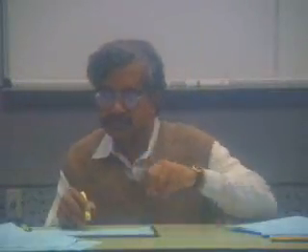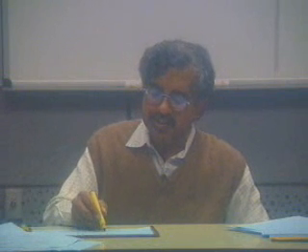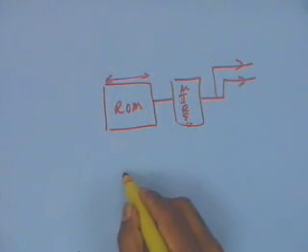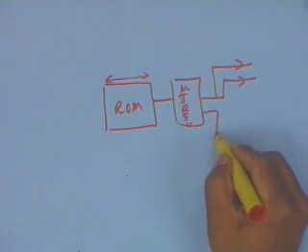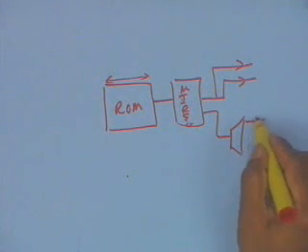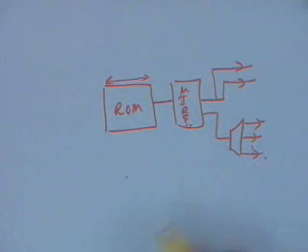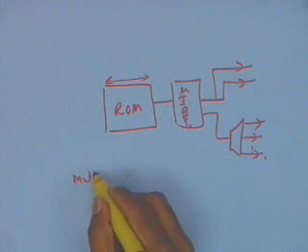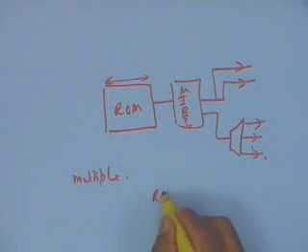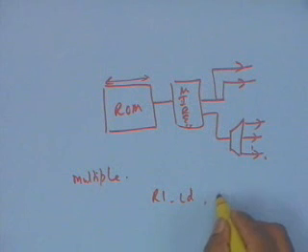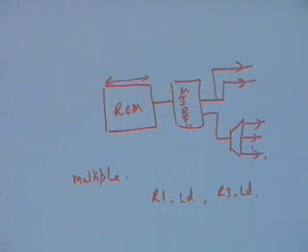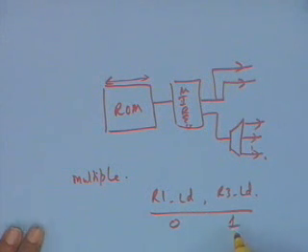When we have multiple control signals into the same field, then we need the decoder coming from here, which can generate this. When we have multiple control signals, let us say R1 load and R3 load, let us say we merge both of them into the same field. Then we have to say that 0 is R1 load and 1 is R3 load.